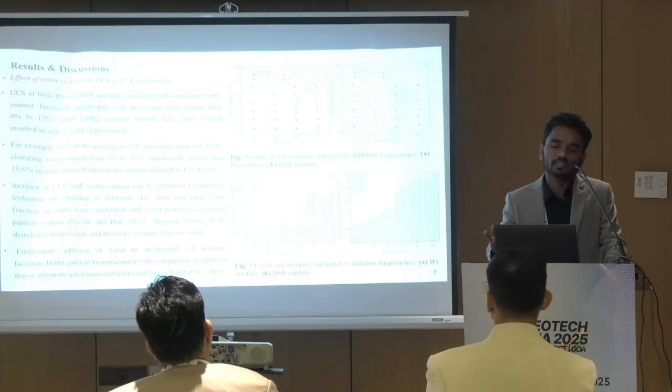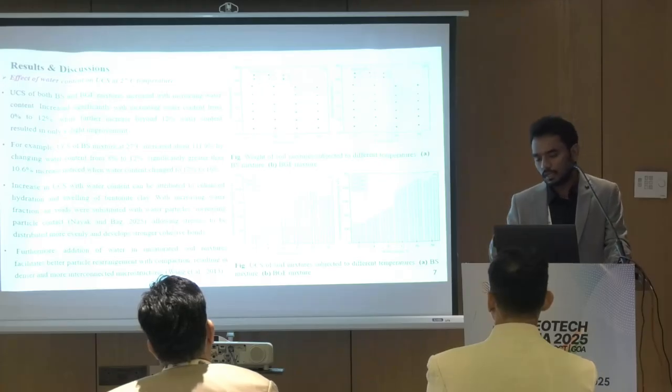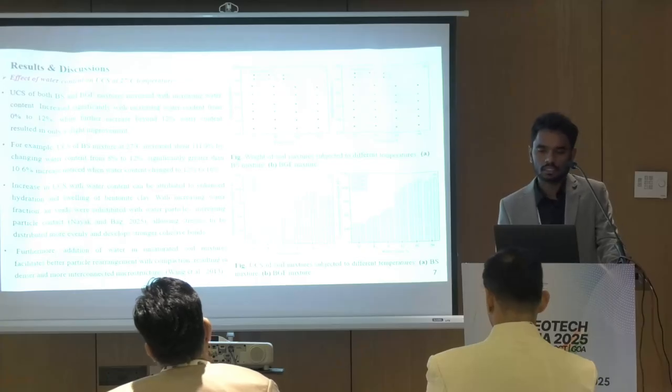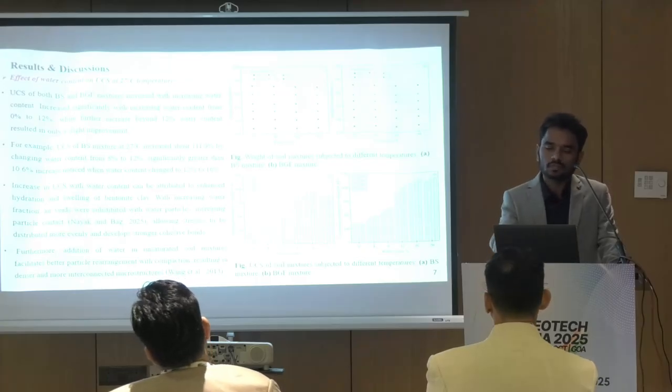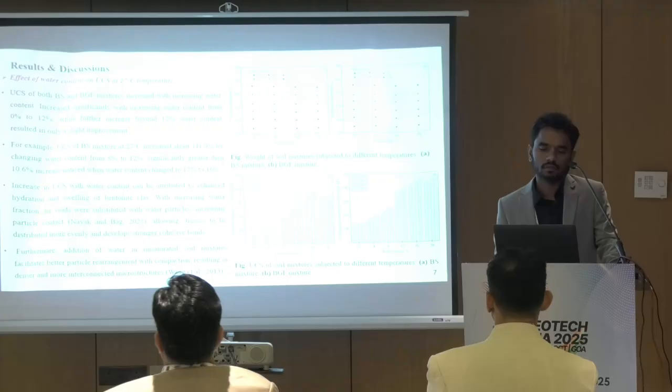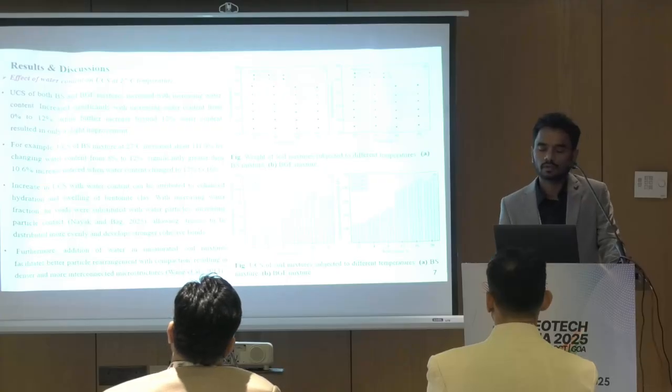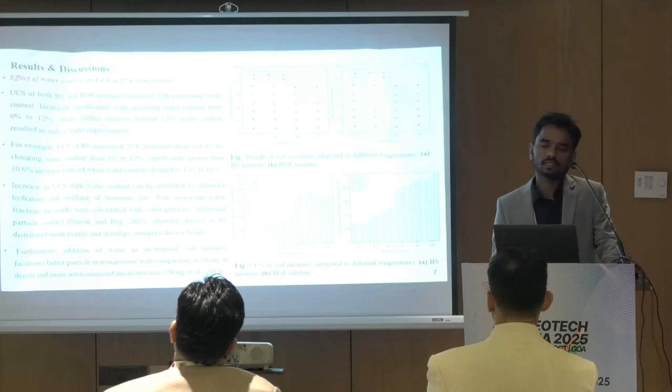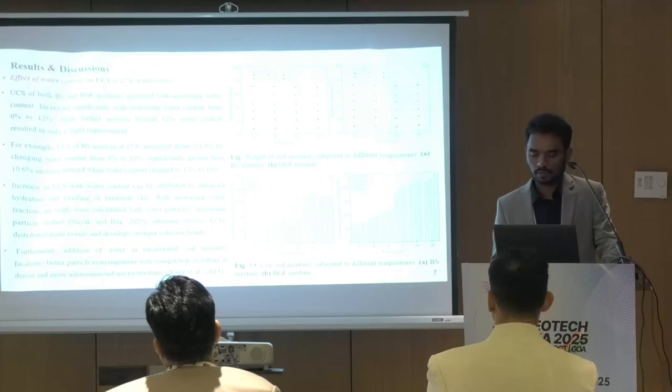At different temperatures, we checked the weight of the sample in order to see any changes in the specimen condition. There is not much change in the weight of the specimen. Only a small amount, around 1 or 1.2 grams, was lost. So this weight loss can be considered negligible in terms of the effect on the test results.